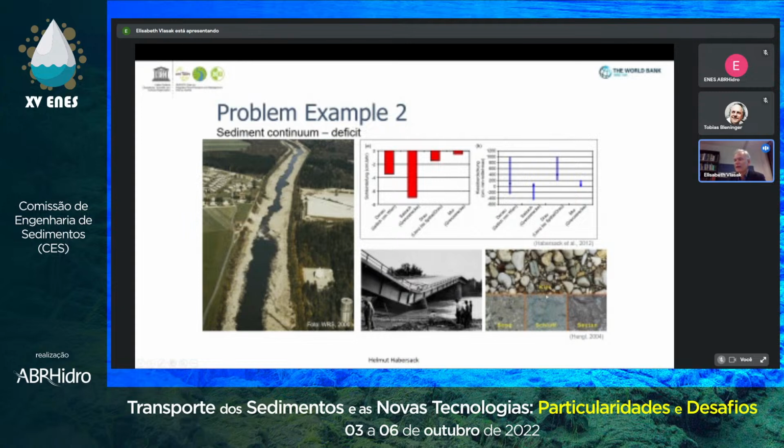And if you reach this line, you get a canyon type of erosion. I mean, this is the extreme case, just to show you it's not always like this, but it can be like this. And then, of course, the fish cannot spawn because they cannot jump on the dry gravel bar. For the next flood, you have an issue, and so on, or you have a bridge somewhere that might collapse. So we don't want to get into this area.